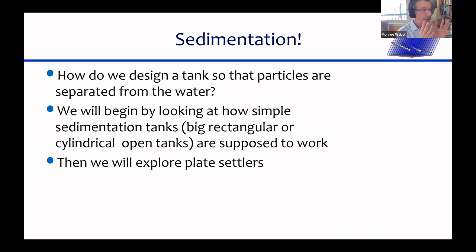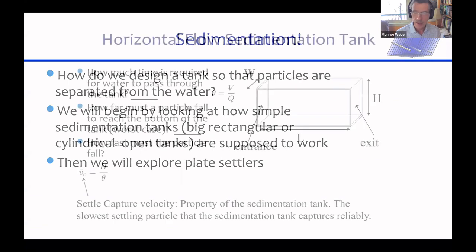Okay, but now to the next task. We want to get the particles out of water. We've got green and red flocks and particles going up through plate settlers, and we'd like to capture as many of them as we can and send them back into the flock filter. So we're going to explore plate settlers.